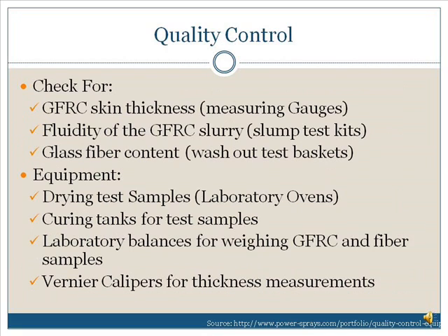Quality control for GRC includes checking the thickness, the fluidity, and the glass fiber content. The equipment needed for such measures is drying ovens for test samples, curing tanks for test samples, lab balances for weighing GRC, and vernier calipers for thickness measurement.